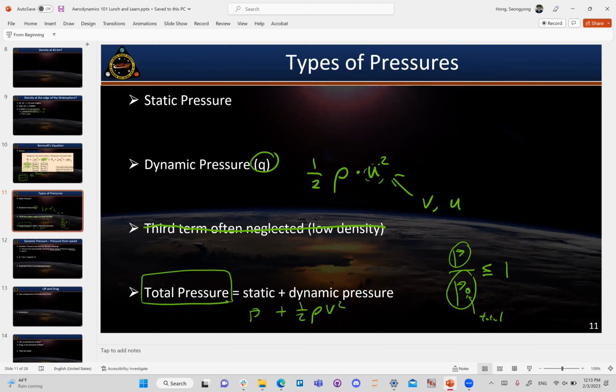And the size of this ratio matters. If you go to wind tunnels, aerodynamicists take total pressure readings and static pressure readings, and that ratio often tells them how fast the fluid is moving inside the tunnel itself. And this is actually how a device called a pitot tube operates. It takes the ratio between those two pressures and enables you to spit out a velocity of your aircraft. So, pitot tube, that's how it's spelled.